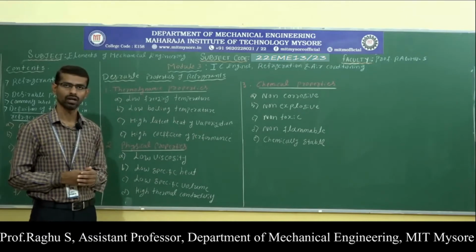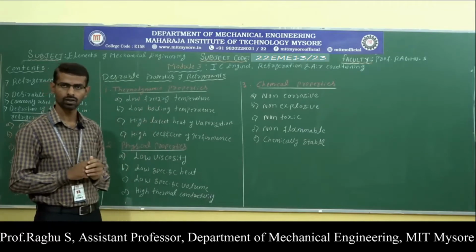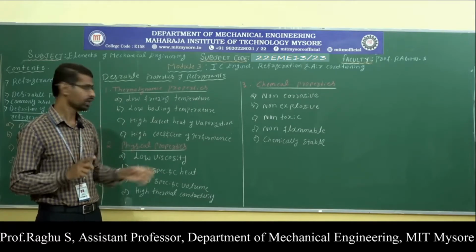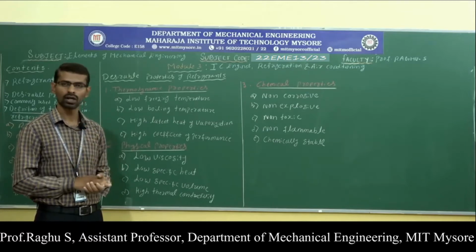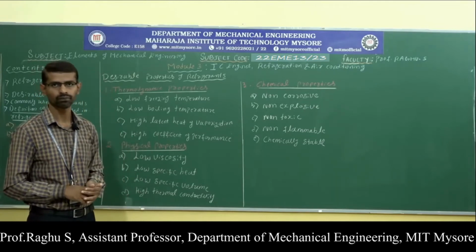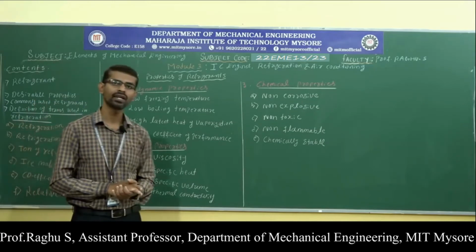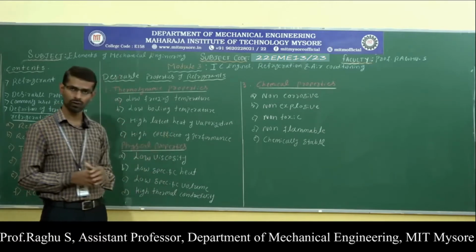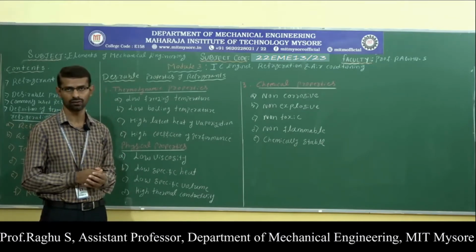Thermodynamic properties. First, a good refrigerant should have low freezing temperature, so that it will not freeze at very low temperature, and at the same time it should have low boiling temperature also. Then high latent heat of vaporization. When a refrigerant has high latent heat of vaporization, it produces a high refrigeration effect, meaning high cooling effect.